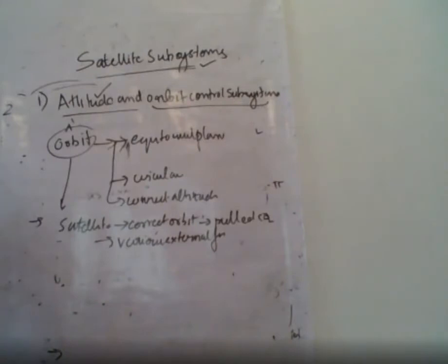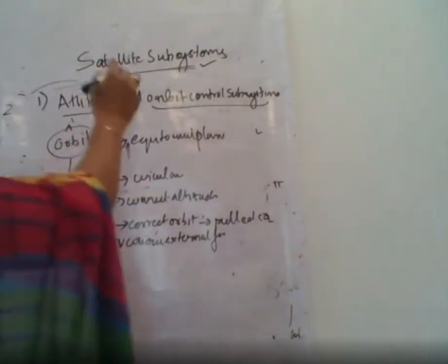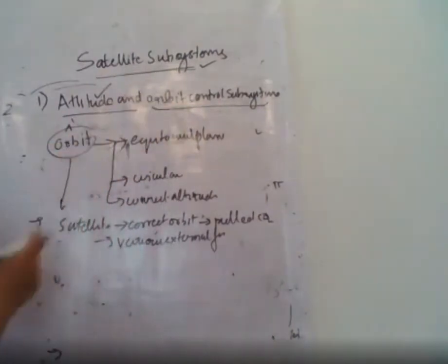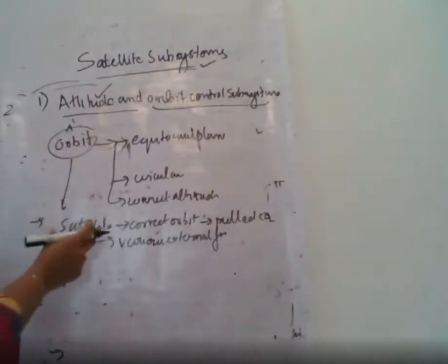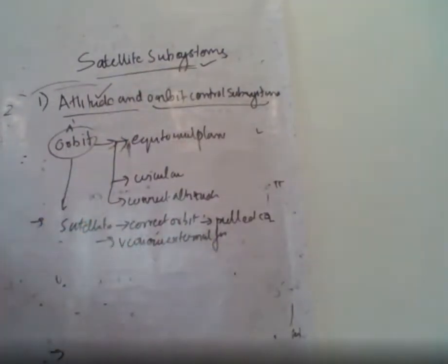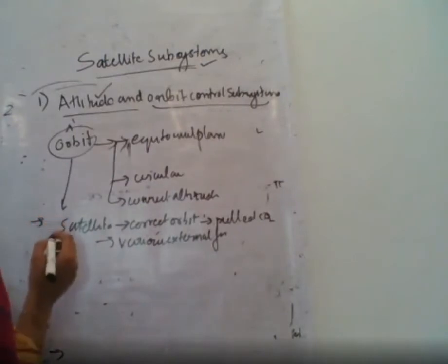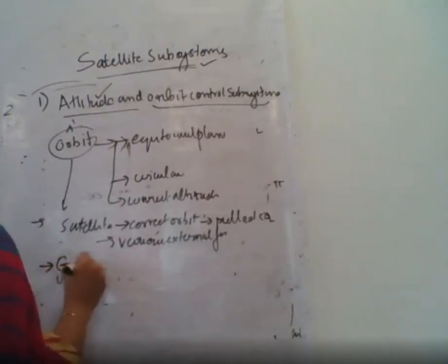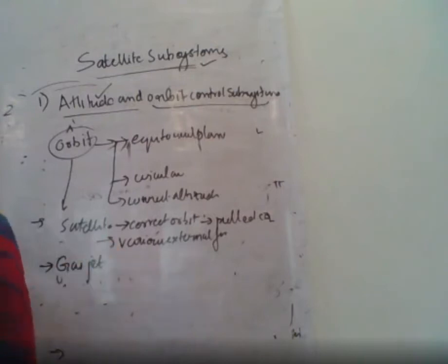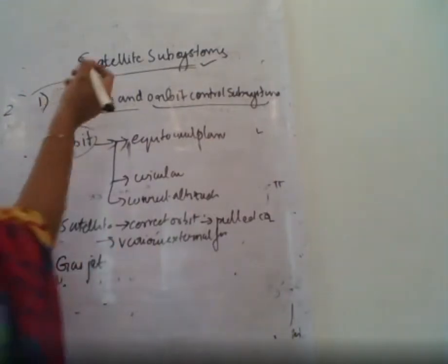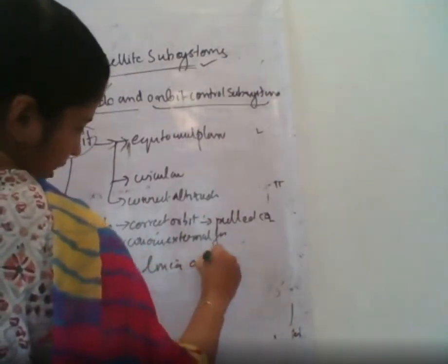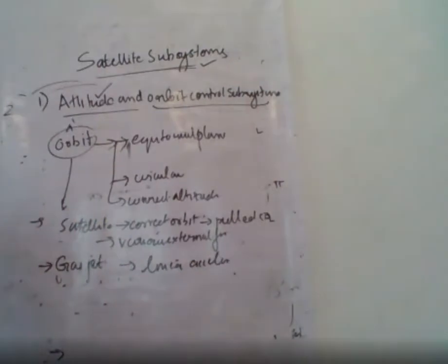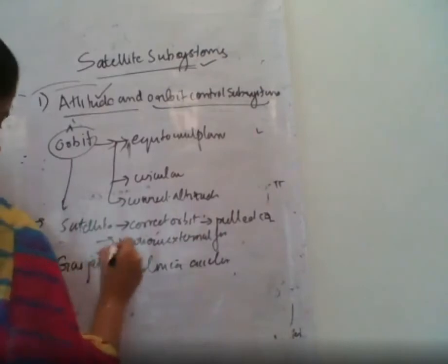It is the function of the orbit control system to return the satellite to the correct orbit. By using this orbit control system, we can return the satellite to the correct orbit, and this can be done with a gas jet. It cannot be done with a momentum wheel, since here we require a linear acceleration. So we cannot use momentum wheels, which we used in the attitude control system. Here we use a gas jet.